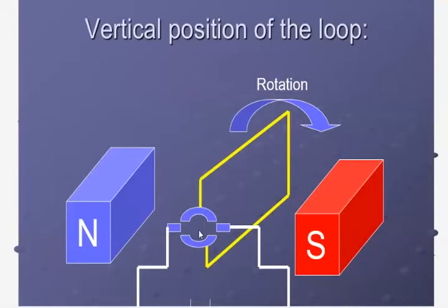If equal and opposite forces act along the same line, then their vector sum will be 0 and their turning effect is also 0. That means no turning or rotational effect will be there. So due to these two forces acting on the width arms of the rectangular coil, no turning effect is there.